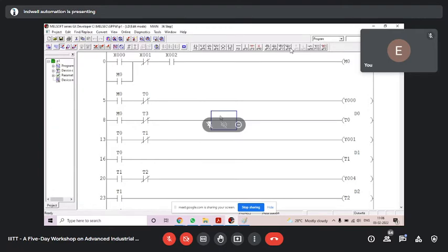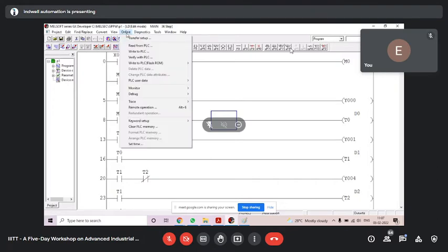Okay. Now you people have to answer. Yesterday we have done all these things. Tell me, for communication, what are the steps? You tell me the steps, I shall follow here. I have to check communication, PLC and laptop communication. Click online. In that, click transfer setup, sir.